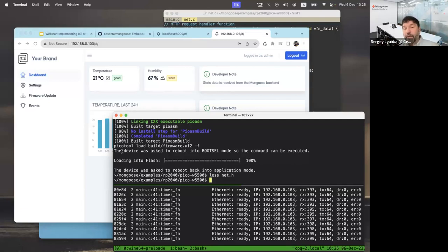And there is a standard protocol for that. It's called MQTT. The MQTT protocol is designed for exactly that, so that embedded devices can make an outbound connection to the MQTT server, and then use a publish-subscribe mechanism to exchange data. An MQTT client connects to the server and says, I want to publish data on this topic.